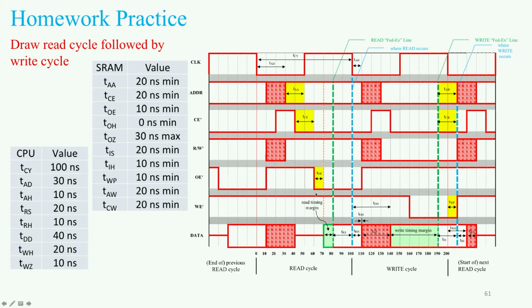So at this point, once output enable flips low, we can see that chip enable is asserted, the address is correct, output enable is asserted. Those are the three things that you've got to have set up before your SRAM will start, and the read bit is obviously set to a read operation. But remember, the SRAM isn't actually reading the read bit. It's not actually an input to the SRAM. The only inputs to the SRAM are the address, the chip enable, output enable, and write enable. And all three of these things are set up and stable at this point.